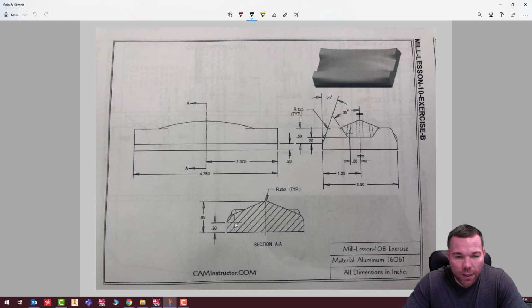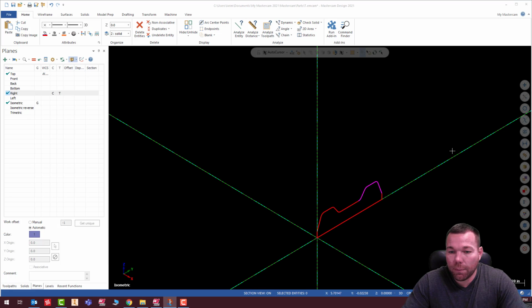So we're going to need to create this arc. We don't need to create this arc. We can actually just radius that, create a fillet there. So I am actually going to draw this line, this arc, and this line and extend it past it. I'm just going to mirror it. We're going to trim it and radius it. All right, so let's go ahead and do that.